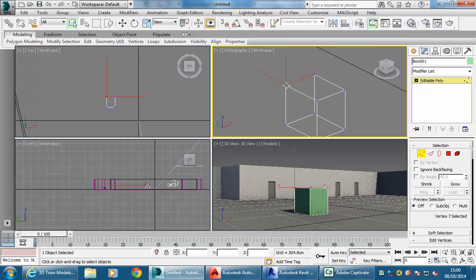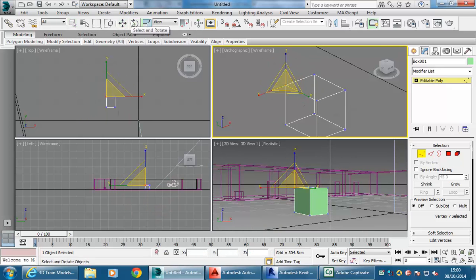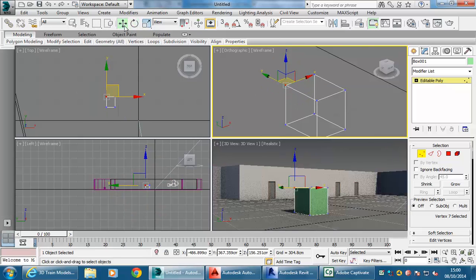No. So if you remember in Revit, when you're working with massing, it's got a different icon to show you when it's going to move. And you have that in 3ds Max. It's up here, it's on select object. Go to the right and you've got there select and move, and the other ones rotate and scale. So they're your main transform tools, just like in AutoCAD and Revit. So with select and move, you get the gizmo, which shows you the different axis directions, X, Y and Z.